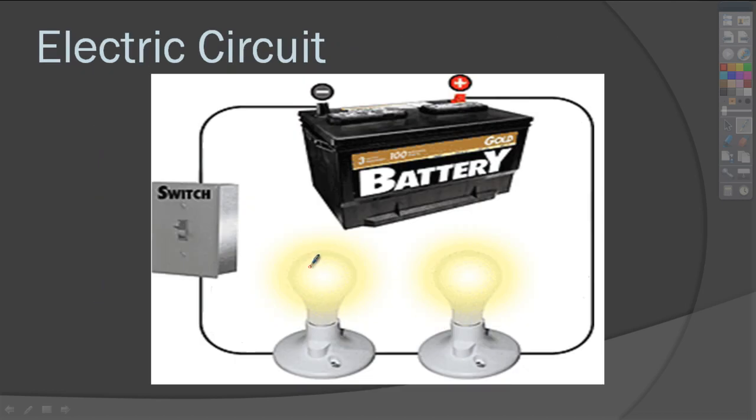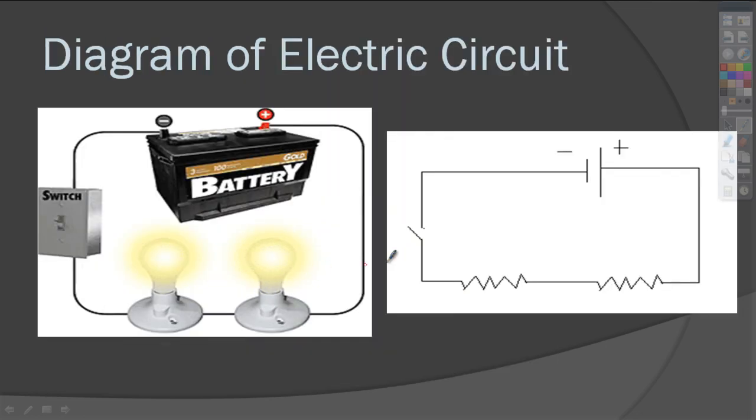So if I wanted to draw a schematic for this one, this one would be pretty easy. First we draw on our battery, long side, short side. Long side's positive, short side's negative. We draw our wires around. Oh, we hit our first light bulb. So it's a resistor or a user. Nice straight conducting wire till we hit our second light bulb. Nice jagged line. Then we follow it around. Then we draw in our nice little switch that we can close to complete this path.